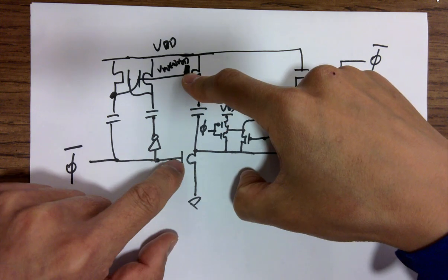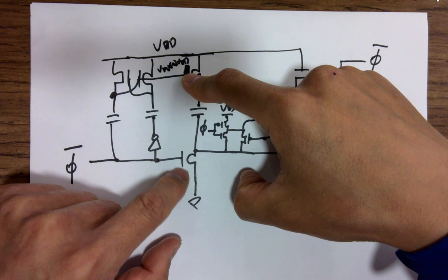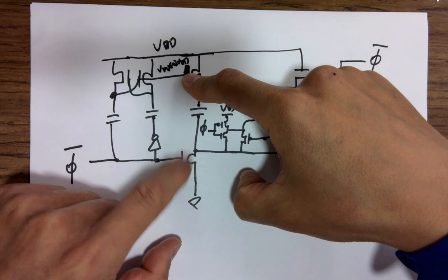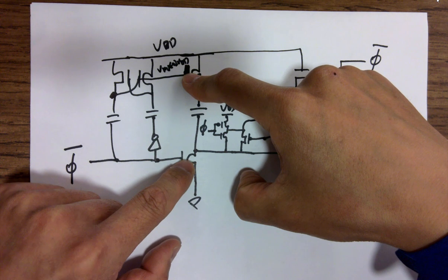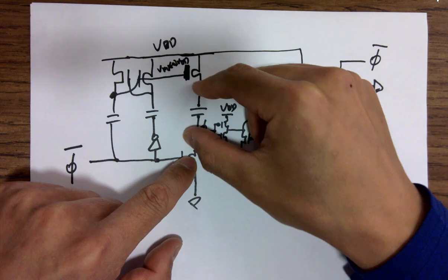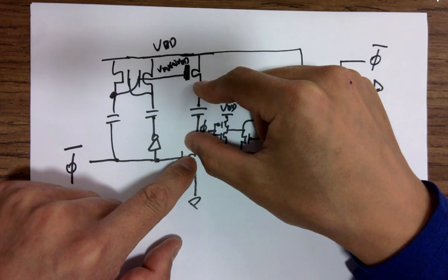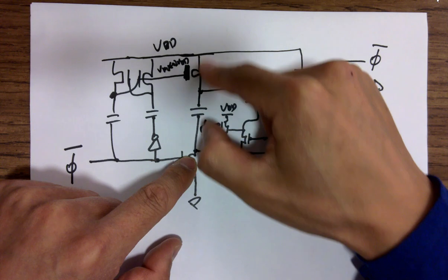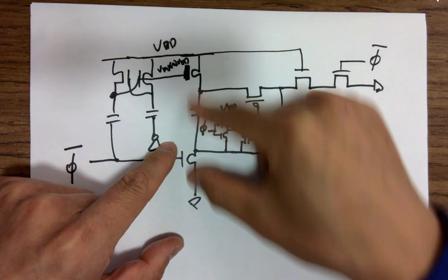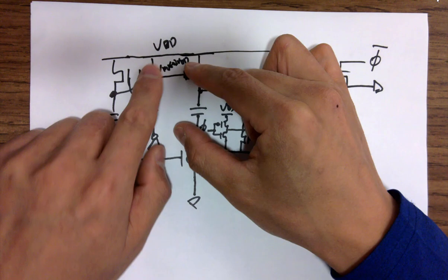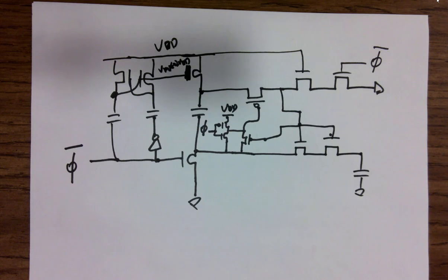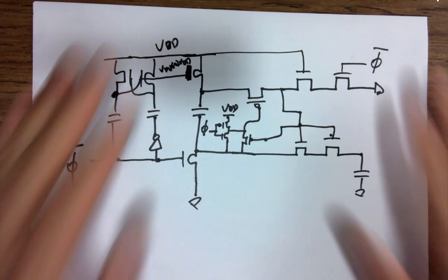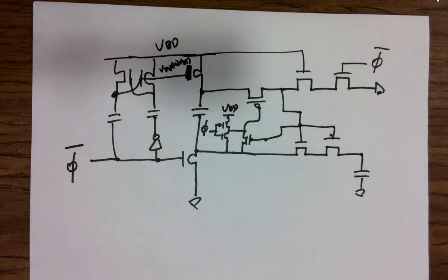The falling edge to the NMOS, is this NMOS on or off? Off, okay? So did you store a VDD across the cap previously? Yes, because you turn it on, it pulls. And this was on, so it pulls. Whenever this is on, you can imagine, even though it's just drawings on the paper, it's actually something happening.